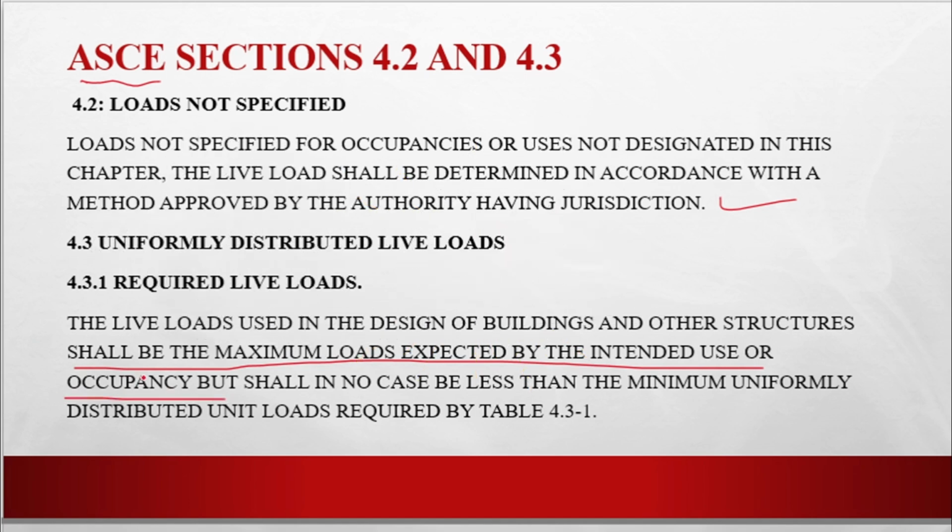So if any intended use or occupancy is not mentioned in the document, you will calculate on the basis of your engineering judgment. But the code also specifies minimum uniformly distributed loads, and that is mentioned in Table 4.3-1. So for your buildings, you will see this Table 4.3-1.